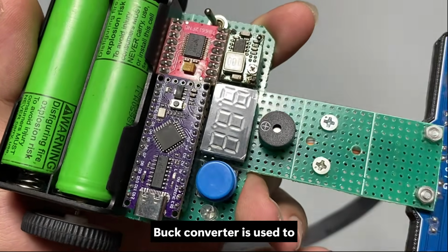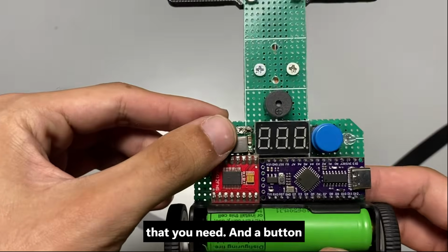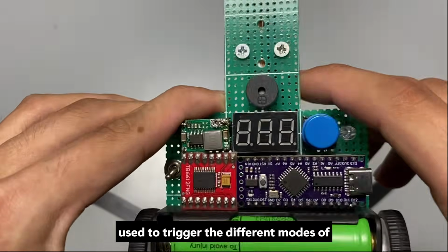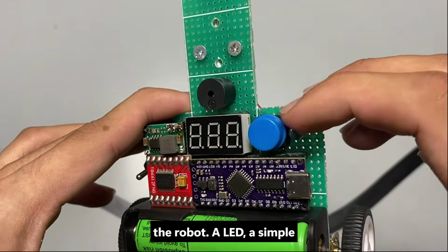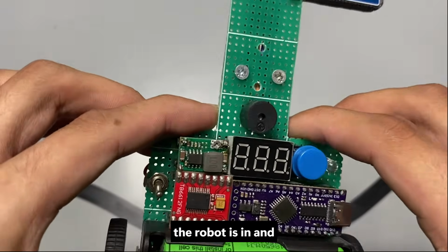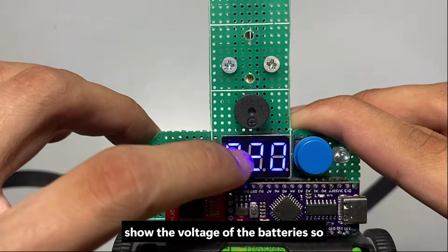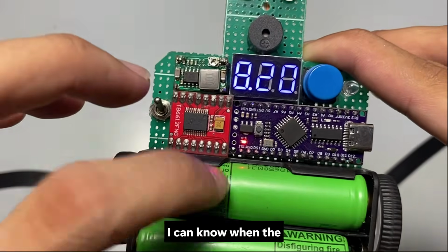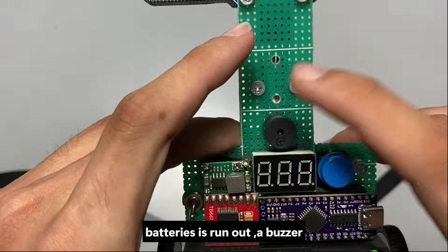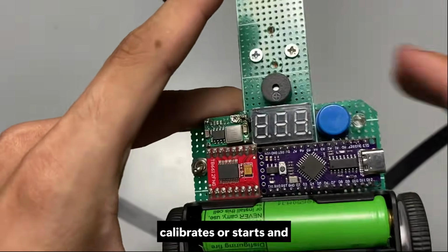The buck converter is used to adjust the voltage to the value needed, and a button is used to trigger the different modes of the robot. An LED, a simple visual indicator to show what state the robot is in, and a voltmeter. It will show the voltage of the battery so I can know when the battery is running out. A buzzer, providing audio feedback when the robot calibrates or starts.